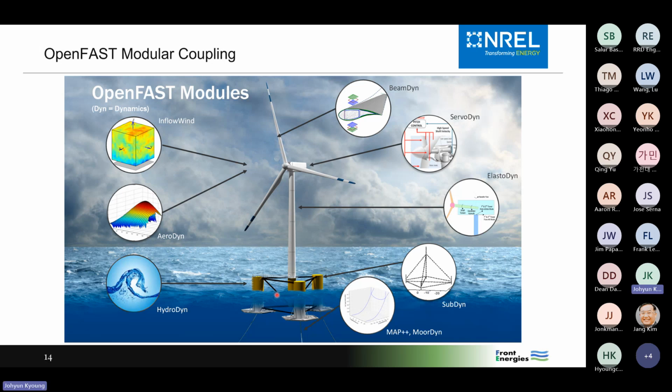Flexible in the sense that it's represented by a beam, but the loading is based on a rigid body. So for the rigid body, for the potential flow, we lump all the hydrodynamic force at a point because it's rigid, it doesn't matter. But for the flexible bodies, like the strip theory bodies, I calculate hydrodynamic loads at each cross section, and I pass them over to the beam elements.